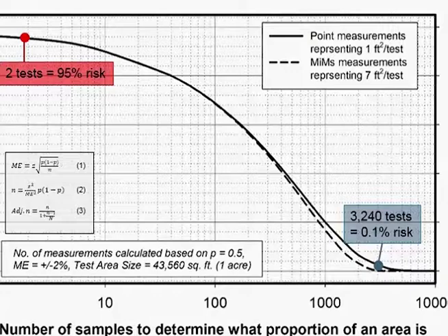And what I saw was damage in some sections, which is great because you learn from it, but it wasn't damage for the whole section. It was damage that was isolated to areas. And you see that a lot on pavements. The whole pavement section is not falling apart. It's isolated locations that are having problems. And a lot of that has to do with variability and not sampling the locations that are going to have problems. So when we look at it statistically,